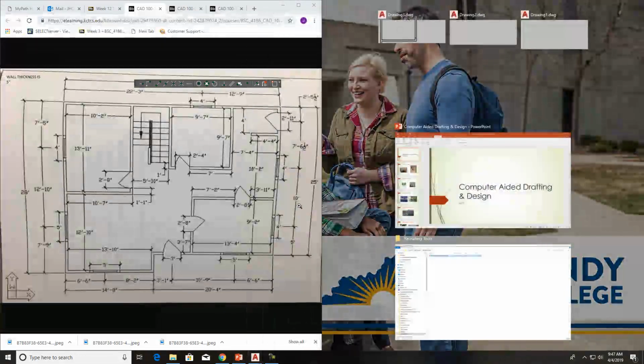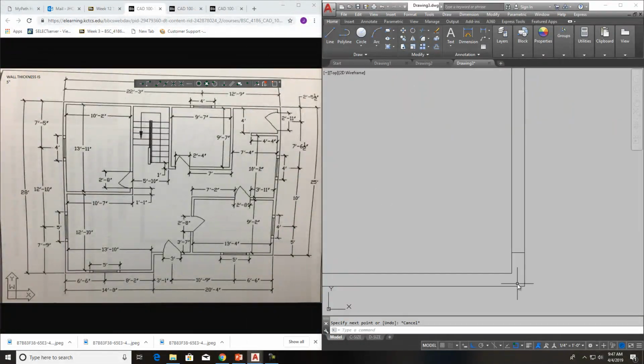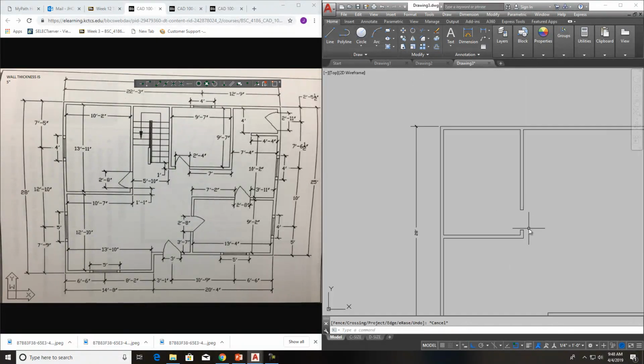And then that door, of course, grab it and we'll sling it over here. And that door is going to be 2'8". Just use an offset, 2 foot dash 8 inches. I use offset a lot. You'll notice that. And then I'm just going to trim out in between, and then just leave it like that.